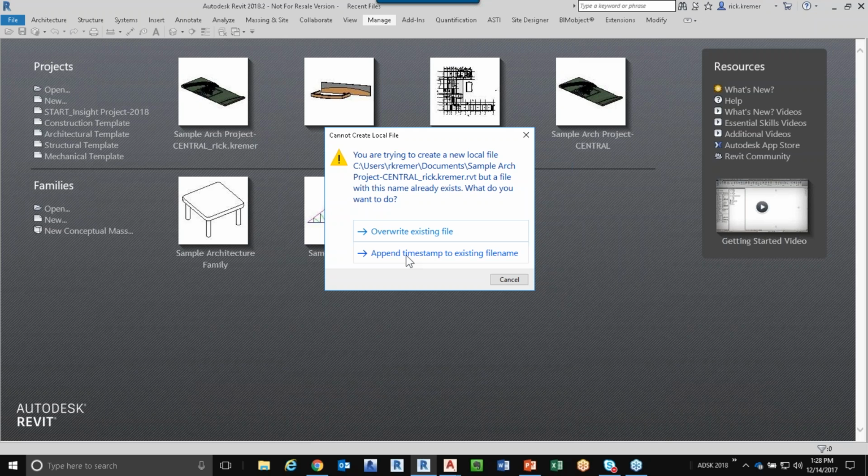Now, remember how we went through and created and restored a backup from the server. Let's say our server, God forbid, got hit by lightning and there are no backups on the server. At that point, you can look at, let's say, the 5 of us that are working on a project and see who has the most recent backup file, and everyone's files will have a timestamp associated with them. So the very first thing in the morning, again, as a recap, open this up and do append. The next time that you close the file and you go away from your desk and you come back and you open it, then click on overwrite. That way you only have one file per day on your computer that is date stamped.